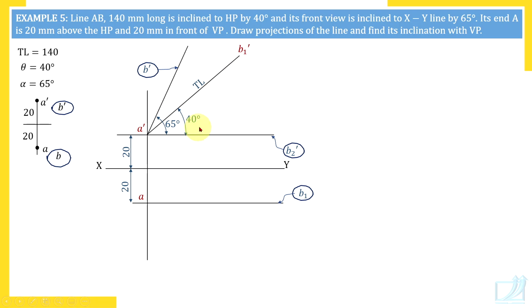Remember now, if an angle is known, say alpha or beta or theta or phi, but the corresponding length is unknown, as in this case where true length is given but length EL was unknown, then you simply draw a line at that angle and label in this manner which other point is on that line.